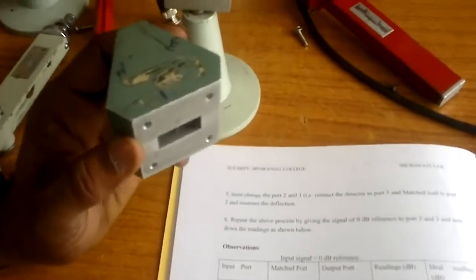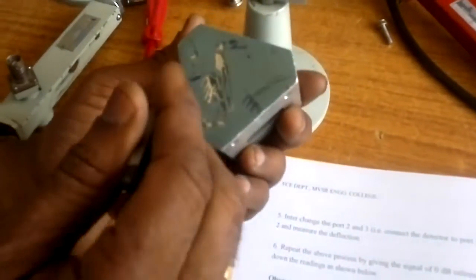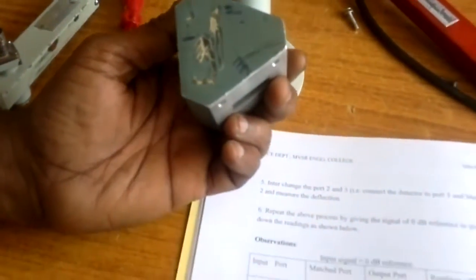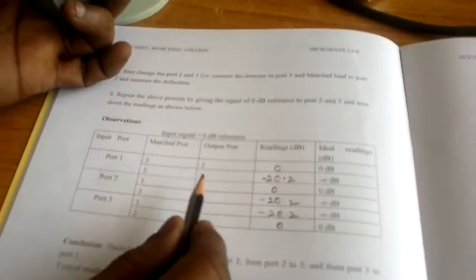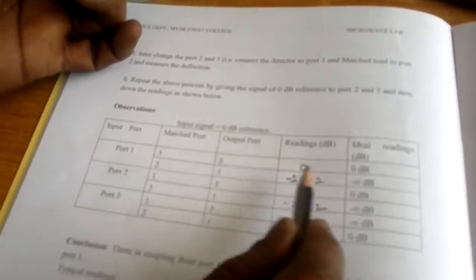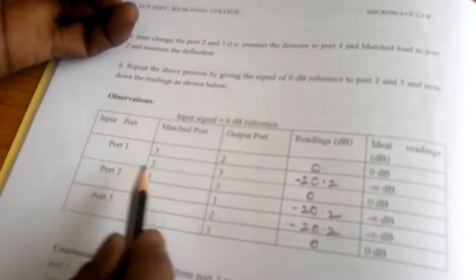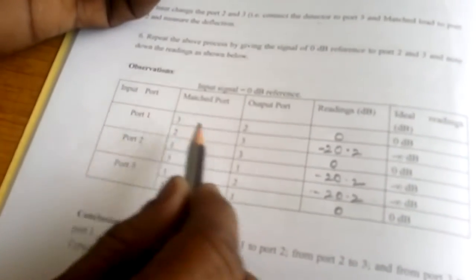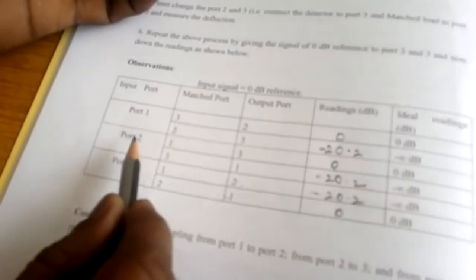In this way, our load is the circulator. 1 as an input, 1 to 2, 2 to 3, 3 to 1. These readings you are supposed to get in ideal condition 0. By doing this experiment, we found 1 to 2, 0. By 2 to 3, got the 0. And 3 to 1, we got the 0. And the isolator part, that means 1 to 3 and 2 to 1 and 3 to 2. These are all the isolator readings.